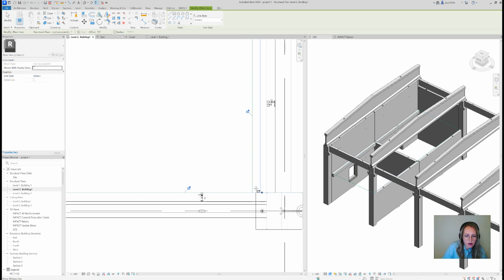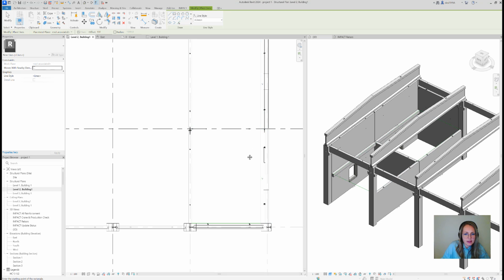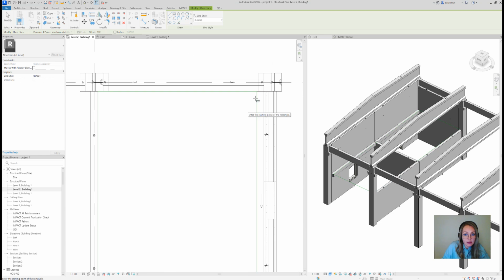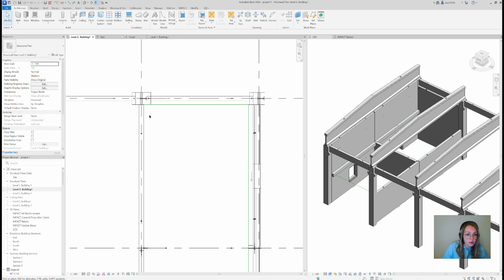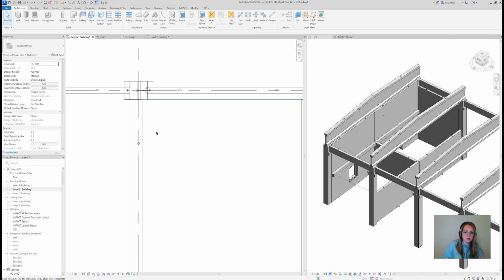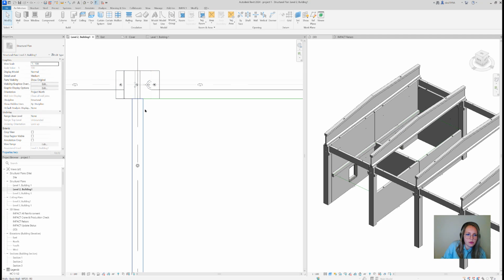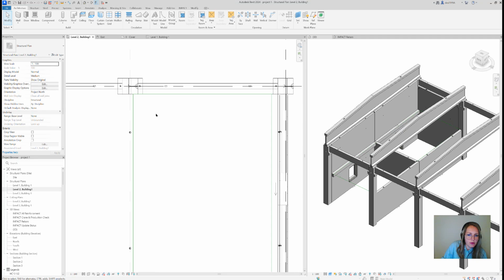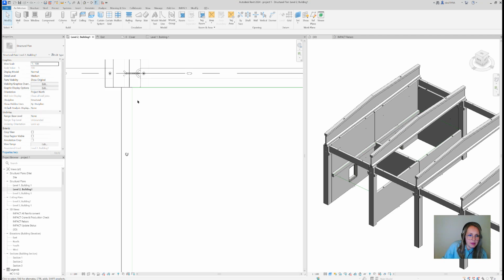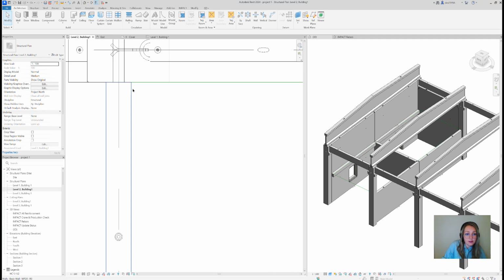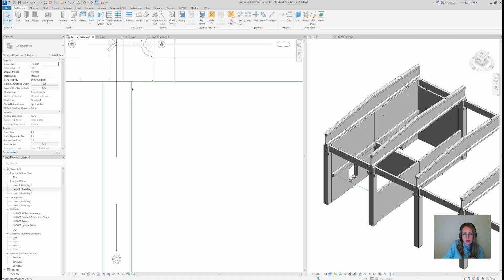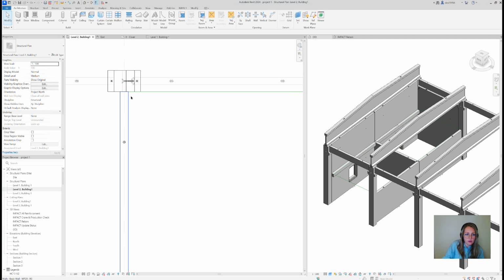But I'm just going to go and make the polyline, the model line on the edge, because I want to demonstrate this support length, which we get a lot of questions and comments about. So I just want to demonstrate what support length is. So basically, we say that our slabs are going to span 60 millimeters inside this hole.